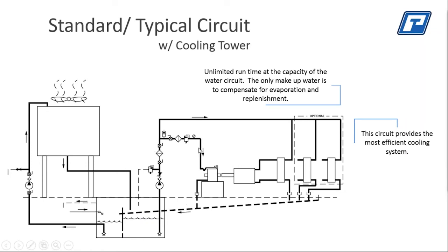A pump is pulling water up and discharging it into the dyno and the cooling system. In fact, I believe, there we go. So now, through the miracle of modern animation, you have cool water being pulled up by the pump, going through a filter, and at that point it is being split off. It is split off to the 3 engine accessory cooling systems and also to the engine dyno itself.